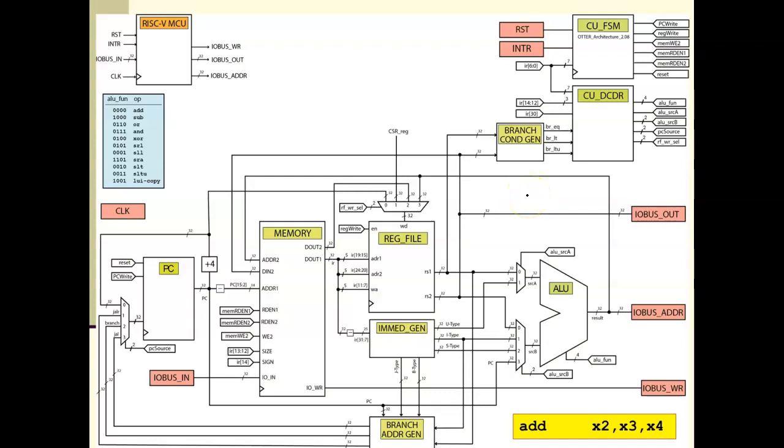Okay, so this is our first instruction. I got it down here. And what we know about this is that these instructions, most of them anyway, require two clock cycles to execute. So this is not a load type instruction, so this instruction requires 2 clock cycles. That's going to be a fetch and an execute cycle.